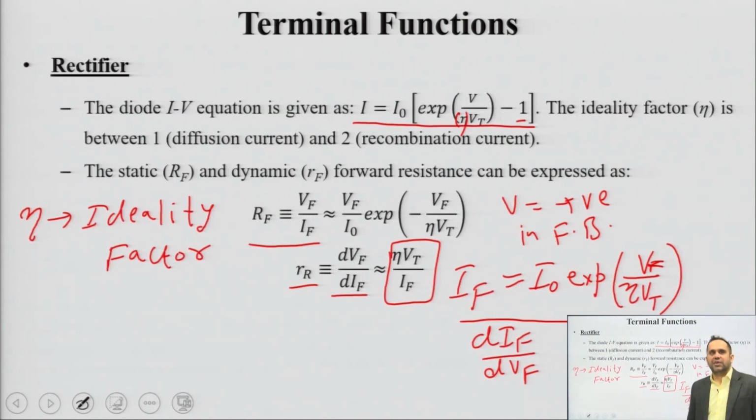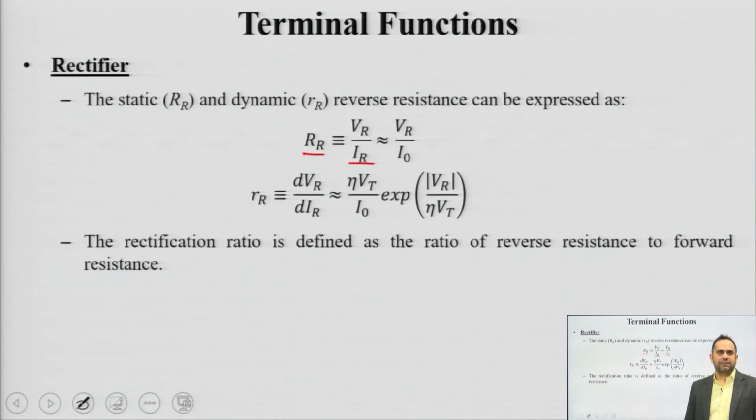Okay. If I go back to the IV equation, when V is negative during reverse bias, this is exponential term. So, this term is very less as compared to 1. So, now I will ignore the exponential term. So, I is nearly equal to minus I naught, the reverse saturation current, during reverse bias. Okay.